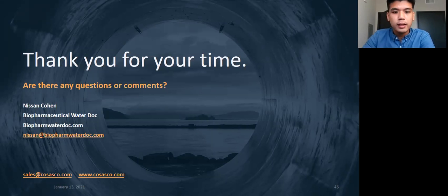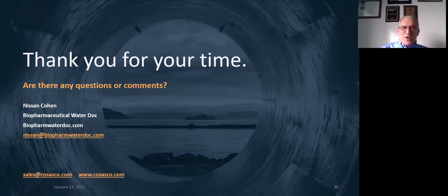So Nissan, one question coming in, what are the NACE standards that apply to this Rouge corrosion? There are no standards per se, except it is stated by the FDA and other regulatory entities that if you have Rouge, you need to have a mitigation system and a plan of how to deal with the Rouge.